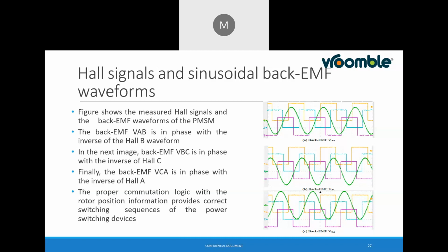That sequence will be continued to create this sinusoidal waveform. Generally, these waveforms are considered based on your total input or the load requirement, which also have detection based on the power and torque characteristics of the motor. And then based on that, the peak power requirement and the peak torque requirement is being designed